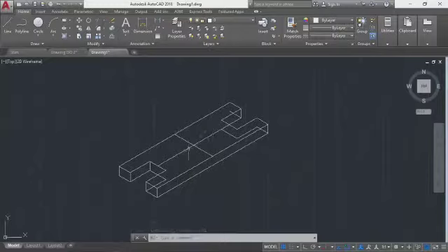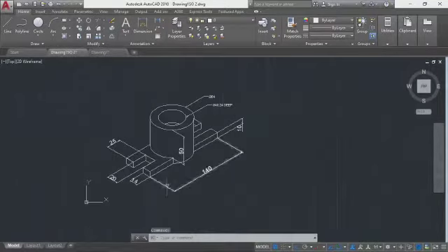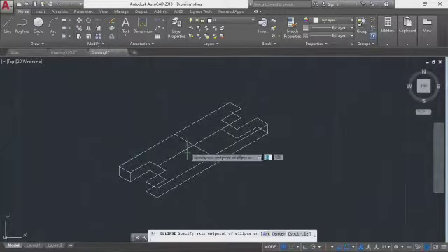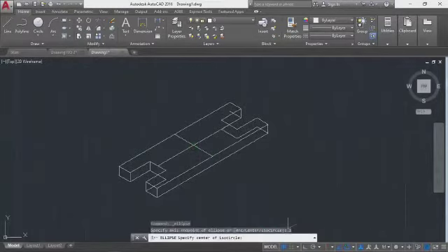But yes, you can. So what do you do with this one now? Is to draw this that you have, to draw your ellipse or your circle in ellipse form. So what do you do now? You go over here to this your ellipse. This ellipse, you click axis end and you come to this middle. But before you click on this middle, you come over here and pick iso circle. So when you pick iso circle, you set ellipse center. Specify center of isocircle. So you specify your center.